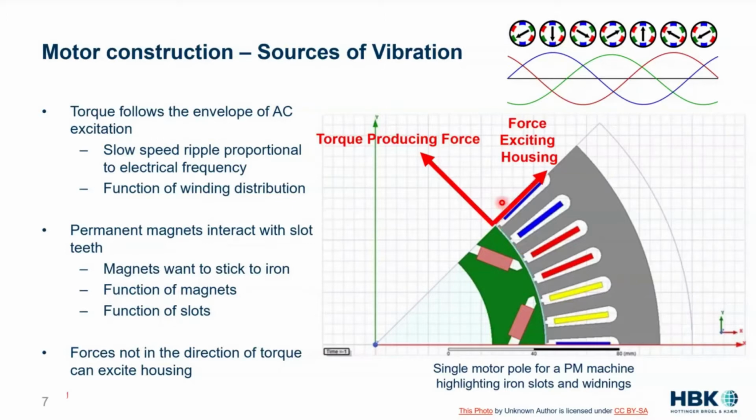And what I've found that's really interesting, and I've been having several discussions about it with customers, is that we can use this excitation, and this permanent magnet ripple and iron ripple, to actually create noise and vibration, and use this for sound design. I'll touch some more on this, but we're really looking to merge these two things for a good experience, but we also want to minimize them in other circumstances for durability and fatigue. So construction has a lot to do with torque ripple and then subsequently noise and vibration.